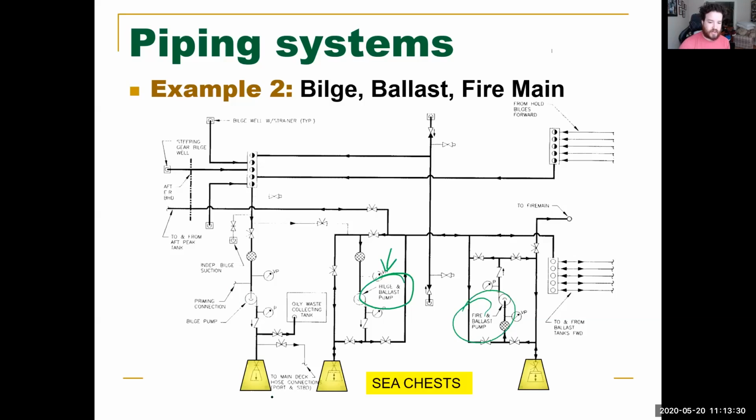Okay. So some terminology, sea chest. What are they? Hold the water. Exactly. It's just basically a box where water enters the vessel. All right. That's all they are. They will have valves pretty much right on them, or a pipe and then a valve that comes right off of it. You know, that's really what a sea chest is.